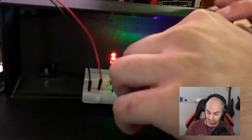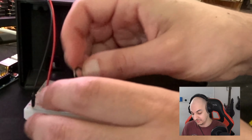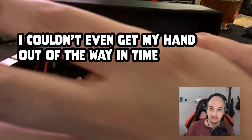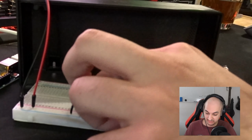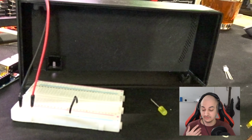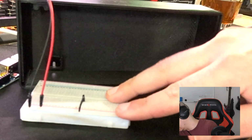Well, it's quite simple. If we would remove the resistor, I'm going to show you actually. So we got a wire going towards ground, and we're just going to directly wire to the 5 volts line, and it's done. See, we're able to tell the LED already died. Let's see if it's hot. No, it isn't, but I'm going to take it out. If we just wire it up to the 5 volts directly, most of the times it will burn the LED and it won't be usable anymore.